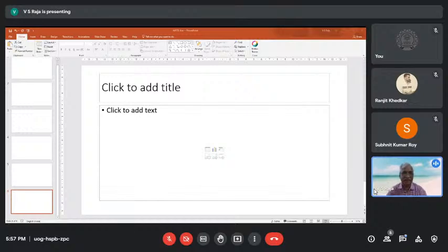The oxygen solubility decreases, and so what is the corrosion rate? What is the corrosion mechanism of steel in water? Iron, right? We consider this for simplicity as Fe to Fe2+ plus 2 electrons. Now this is taken up by oxygen here in neutral water. Okay, this is the reaction, right?